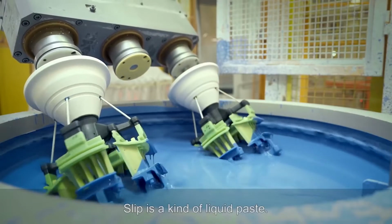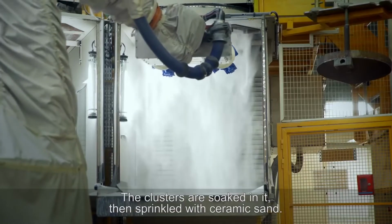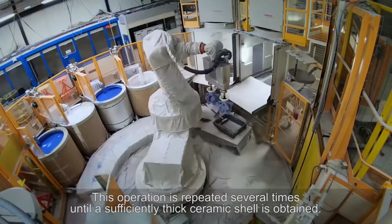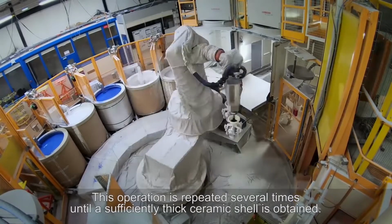Slip is a kind of liquid paste. The clusters are soaked in it, then sprinkled with ceramic sand. Once dried, the whole forms a crust. This operation is repeated several times until a sufficiently thick ceramic shell is obtained.